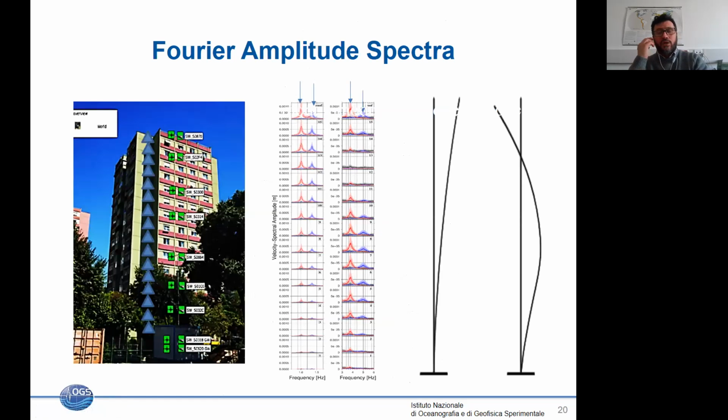Why do we do this? Why in engineering practice is this used very often? Because in a simplified form, you can imagine that a building can be considered as a sort of oscillator. An oscillator that will have not only a first mode of oscillation. This is just a building where we made measurements in Istanbul, and these are results that we will see during the course. A building can be considered as a sort of oscillator with different modal shapes of deformation.